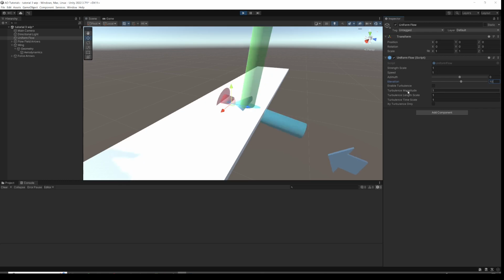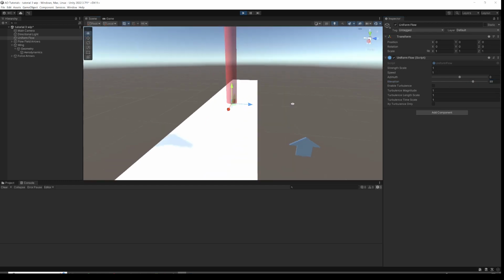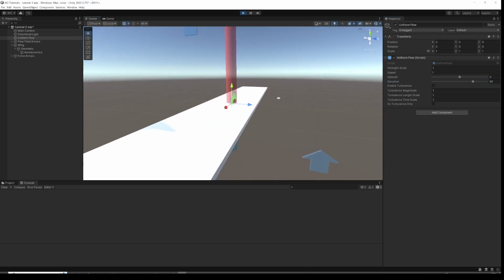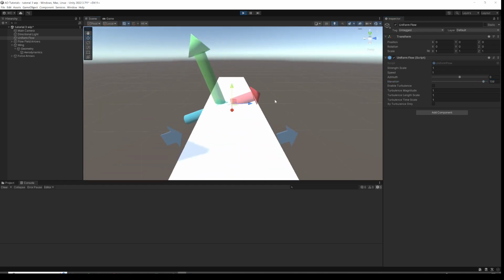So at lower angles of attack, the location of the lift is about a quarter of the way back from the leading edge. But if we increase the angle of attack, what you see there is the aerodynamic centre position moves back until we get to 90 degrees angle of attack, and now the lift, or what's left of it, is acting at the centre of the object. And if we keep on going round and the wing is going backwards, that aerodynamic centre moves round to around quarter chord in the other direction.